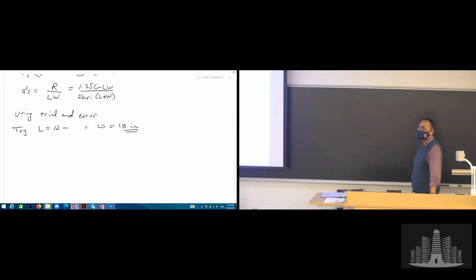Now, you might be surprised that the width is longer than the length, because there is more room for the bearing to go in the width. But in the longitudinal direction, the pier thickness, or the abutment seating area, governs that length. So when we say the length, we're talking about the longitudinal direction of the bridge, or direction of the traffic, if you will.